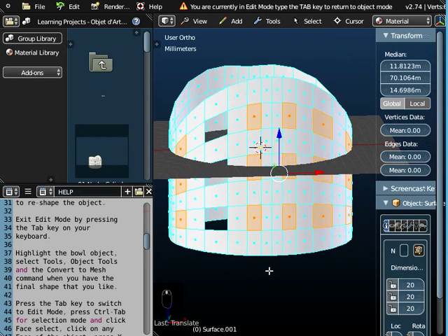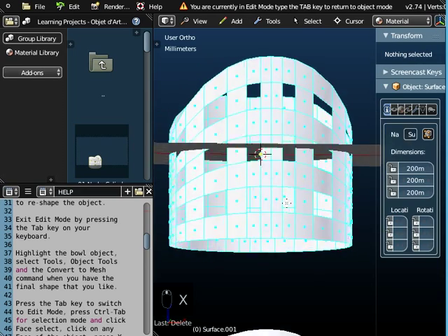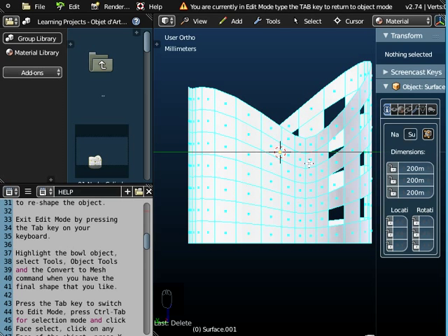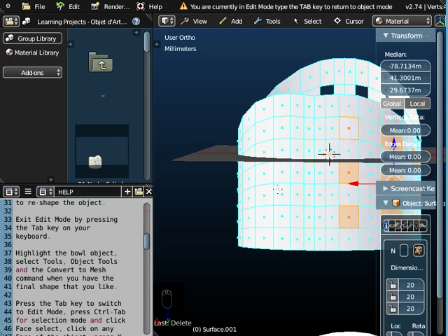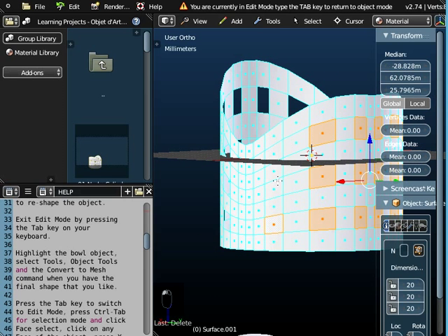Okay, so I've selected them there generally with one gap between them, apart from here because these are smaller. And so now we can press X on the keyboard and delete those faces. So we can delete a lot of faces in one go. And then we could just go round the object and keep doing this. So hold down the Shift key, select multiple faces, just keep going round, stick to the pattern you've already got, and I've just lifted my finger off the Shift key as I rotate this, and just keep going. The more you select, the quicker you'll get the job done.